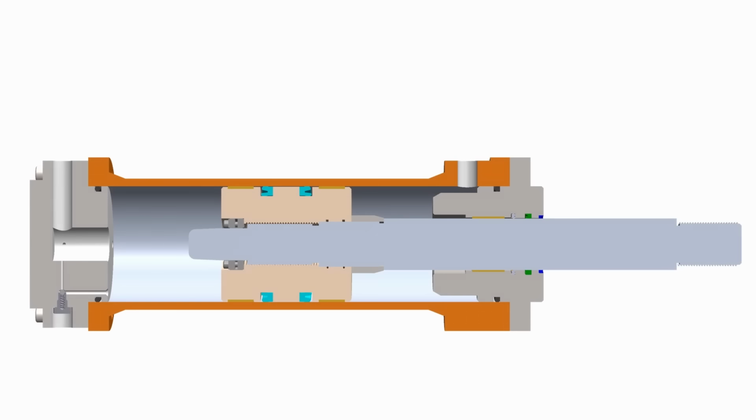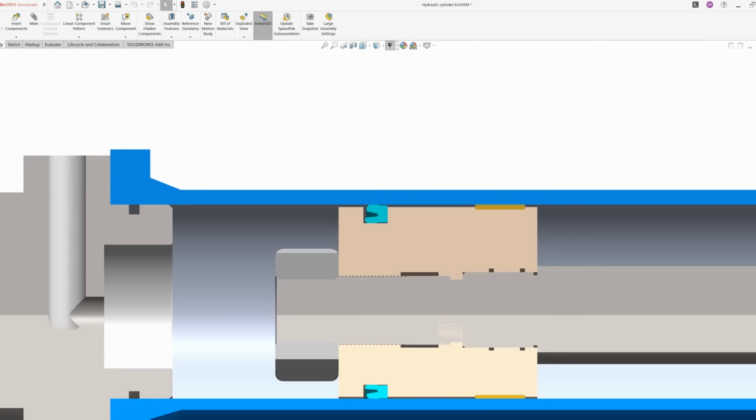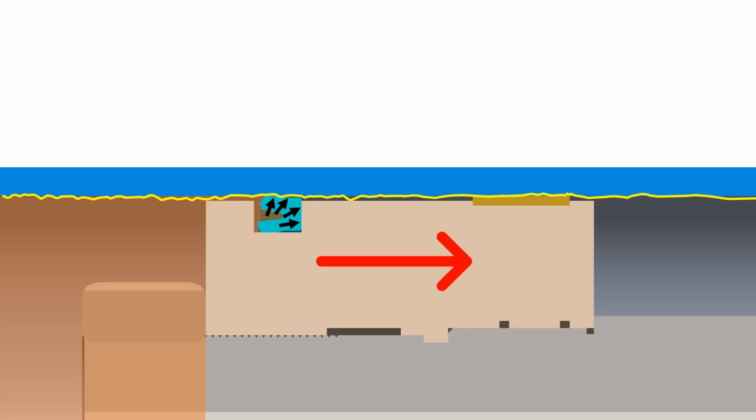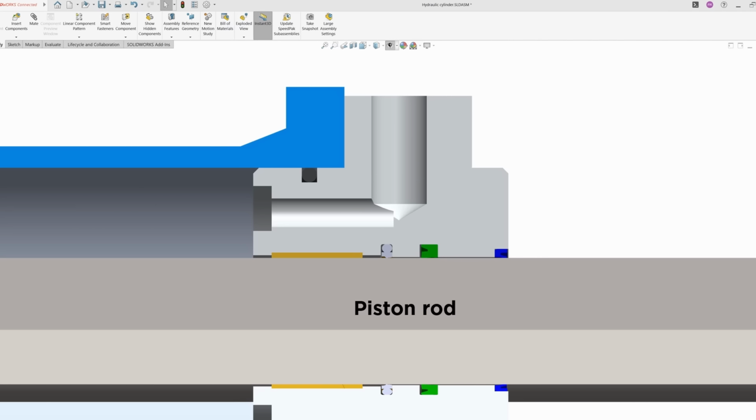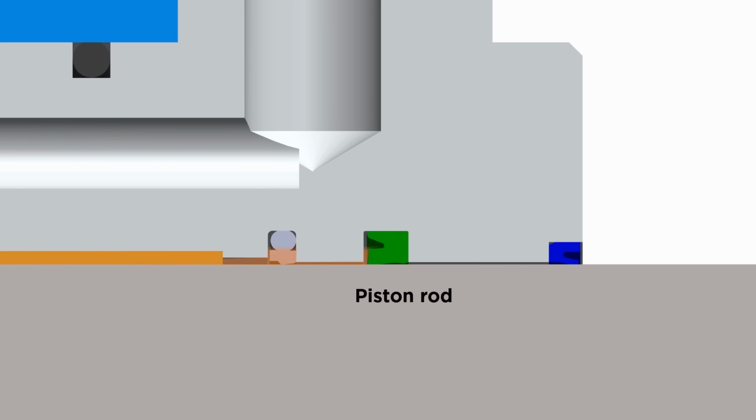Now, for high-speed cylinders, we provide oil cushioning on both sides, on both heads, which we will discuss in a separate video. Now, we also have to understand that when a hydraulic cylinder operates, high pressure applies over the hydraulic seals. So, hydraulic seals run over the cylinder bore under high pressure at high speed. Therefore, a rough surface finish can easily degrade the life of the seals. And the same applies to the piston rod as well, for the rod sealing.